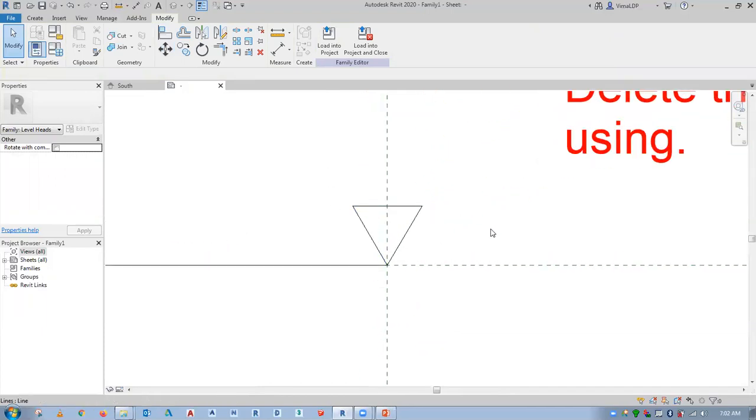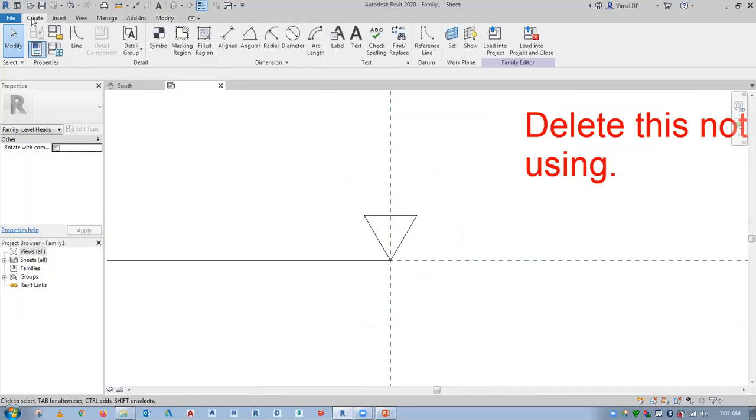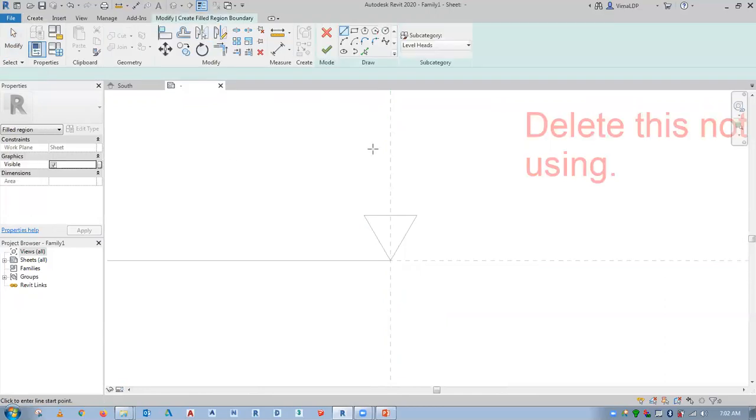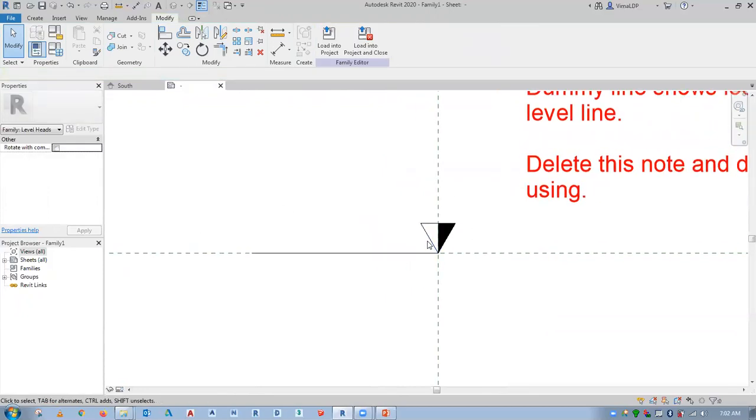And now let's say I want this to be my datum symbol, and I want to create a fill region for that. Maybe I want to create a solid filling within that, or maybe on a triangular portion here. So fill region, once again, I'll go and say pick lines. This time I would lock my elements. Now let's say corner trim. So with the corner trim, I will just trim this area and say finish the fill region. Yes. Okay, now this is okay.